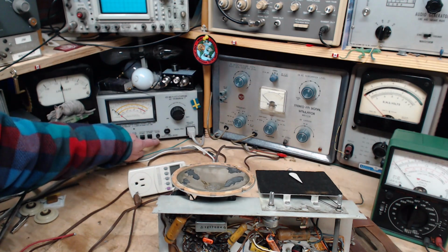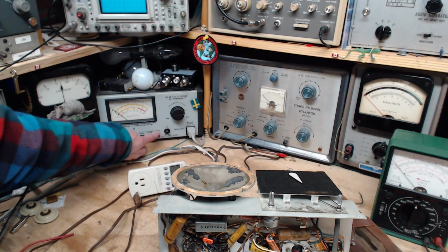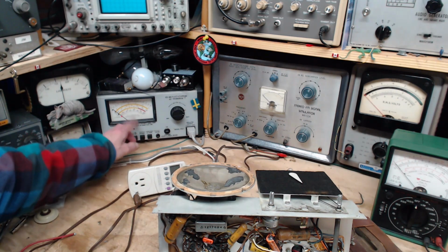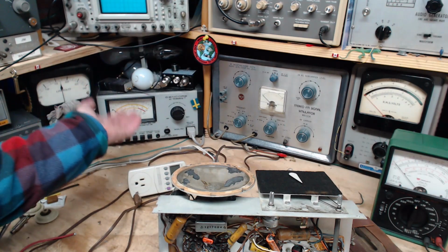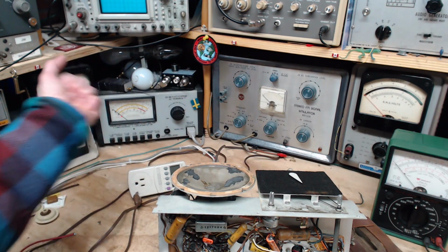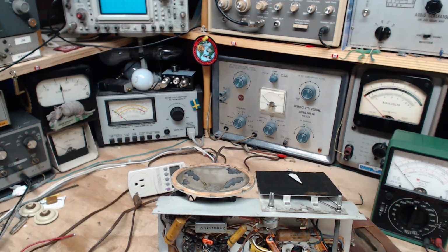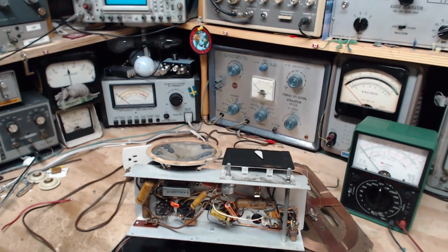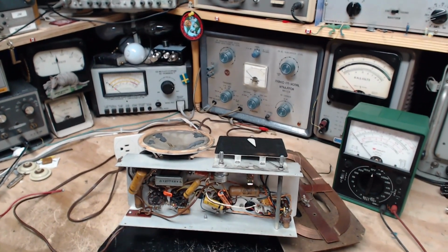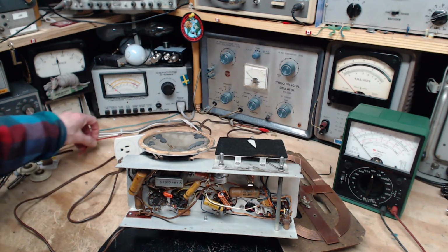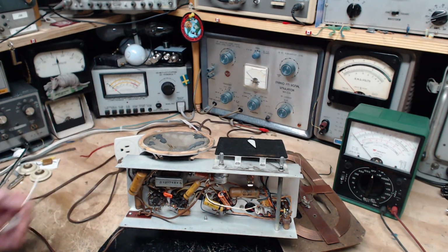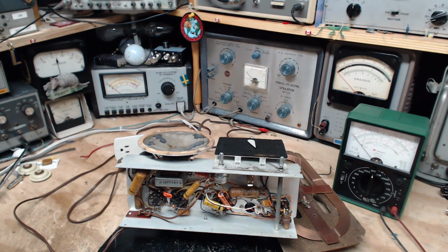I have to find the probe now. This is what we're going to read about and we're going to use. We're going to read this meter. We're going to find out how much current is leaking into this chassis. We're going to find out if it's a dangerous level or not, because there are some values I found in a document. And we can make some judgments about the condition of the radio. I can make a change to it and then make those same measurements again and find out, yes, this worked. No, it didn't work. Oh, here's something I never knew about. That's kind of where we're going with this.